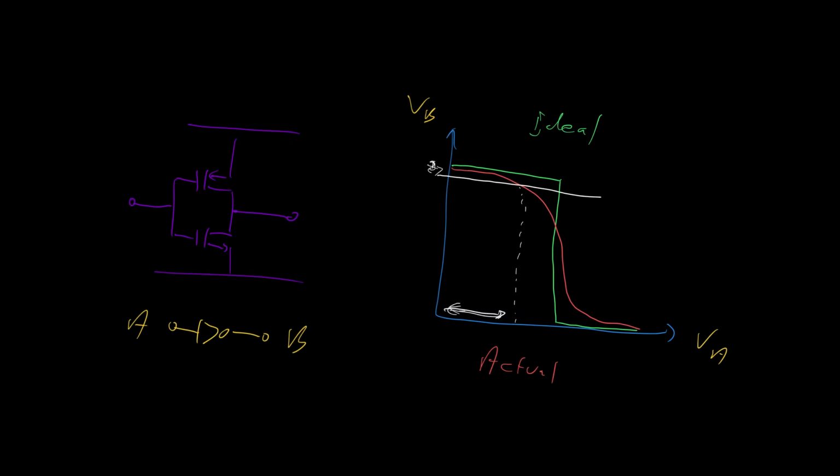The same occurs if the input is high. If we want the output to be very clean, very close to 0 volts, then it suffices for the input to be anywhere as low as, say, 3 volts, 3 to 5 volts. So we can have lots of noise on the input and get very little noise on the output. Every single logic gate is tidying up the signal.